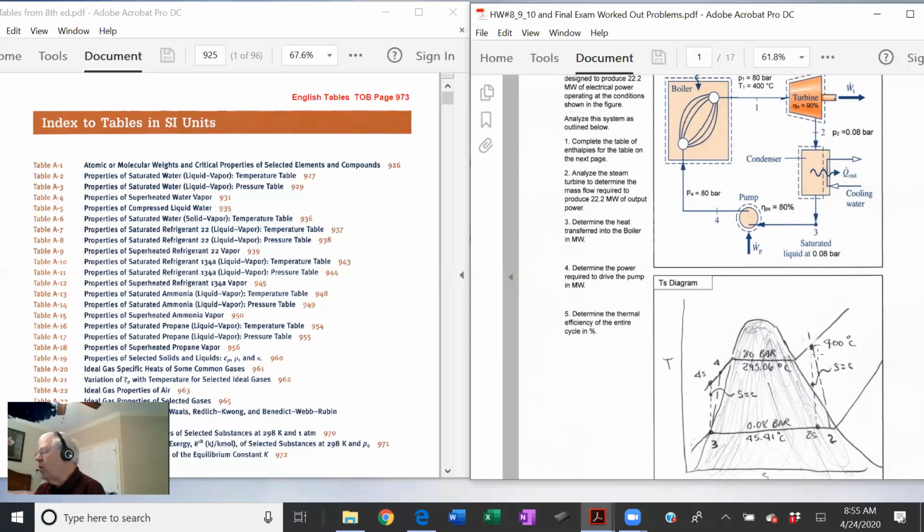And we choose this point on our little sketch because we know when we go constant entropy, isentropic expansion, we're going to hit down here somewhere at about 85, 90% quality level. So we want our diagram to look reasonable. So this is the isentropic expansion through the turbine from the high pressure to the low pressure line.